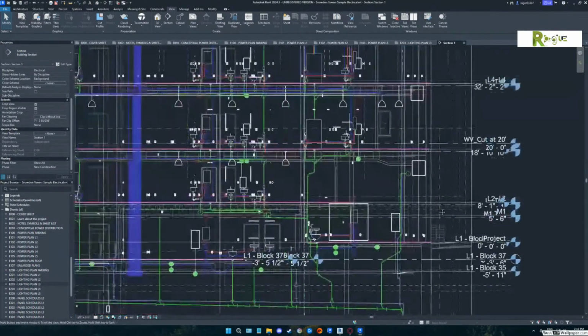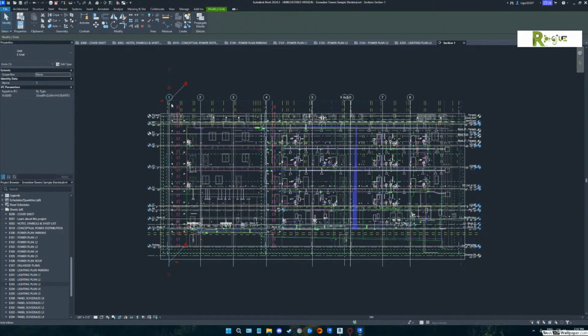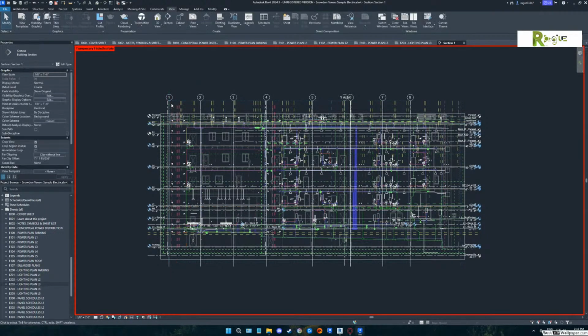Go zoom out. Show me just column line number 1. Yeah, the column lines is only one unit. Take that column line number 1, pick it. Type in HH. See, now that's your one from your Revit link. Well, how is that possible? They're all in the same spot because they're all going to a crop boundary, because this crop boundary is smaller than any other one on the project. So he doesn't have the problem.